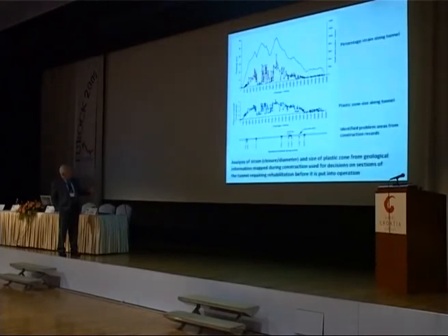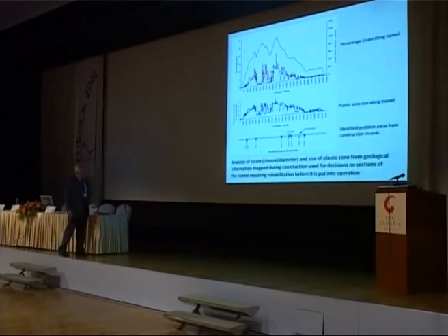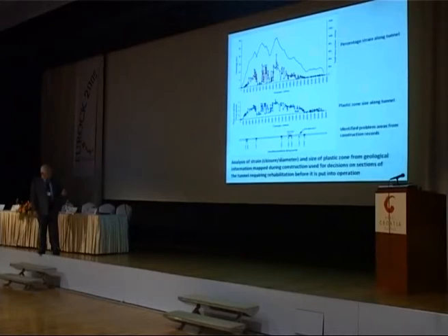What you see here is a record from as-constructed geological information, where the engineers on site have gone back and recalculated the anticipated deformations and plastic zone size. And here you have superimposed areas of known problems. They're going systematically through this, looking at areas that they've got to fix, obviously, because they're broken, or that need further investigation, where they would at least go in and do some drilling to find out if the shotcrete was really what you think it is, and whether things are going to be in order for long-term operation. We expect that process to take about 2 years before the tunnel is finally ready for water transmission.